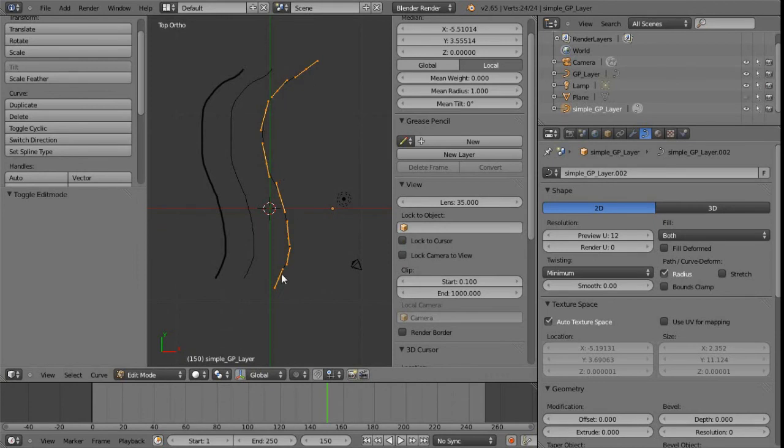In fact, we can see it's 24 points, which is totally fine, which means that it's got 8 individual points along the curve, because this is always going to be divisible by 3. This counts in the vert count. It might be slightly confusing because it's using vertices, whereas maybe other applications use the terminology points, and that's also meaning that it's including the handles as points as well, or vertices in this case.